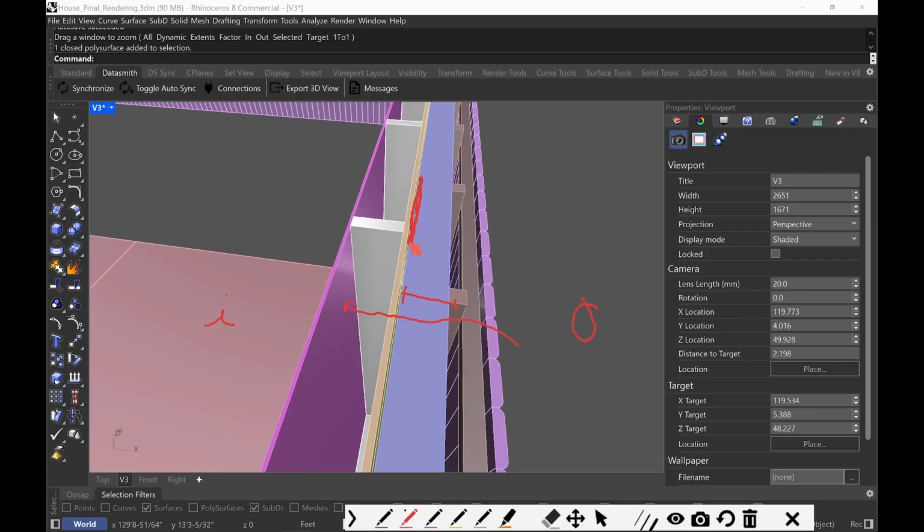And so you can apply this idea for all climatic regions, but you just need to vary your exterior insulation. And you would also vary the permeability of your barrier. Because there are vapor barriers that are permeable, semi-permeable, impermeable.